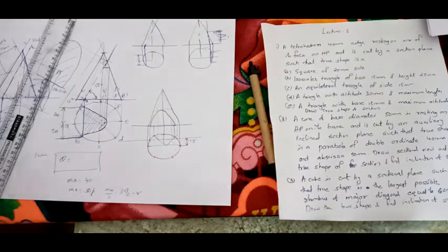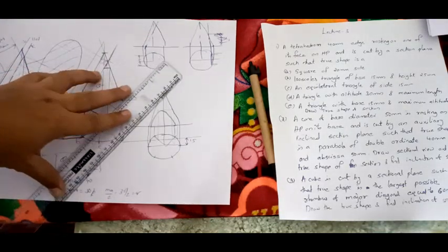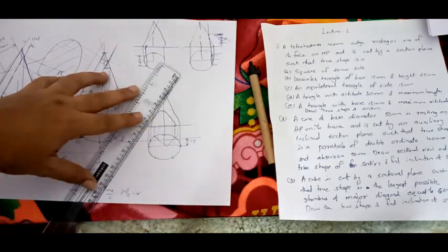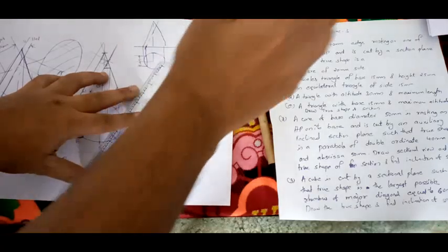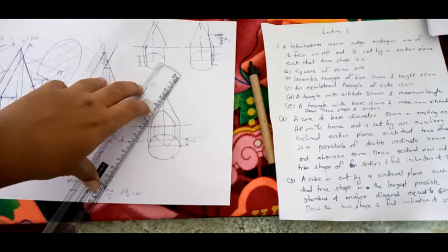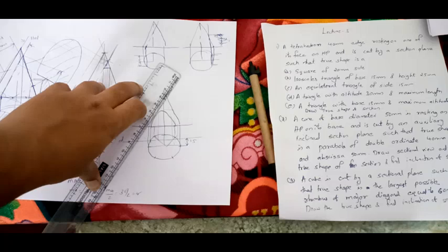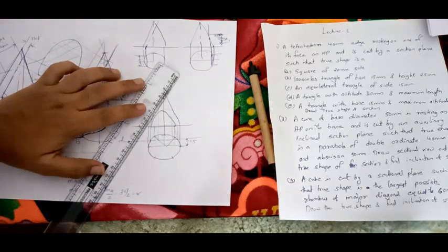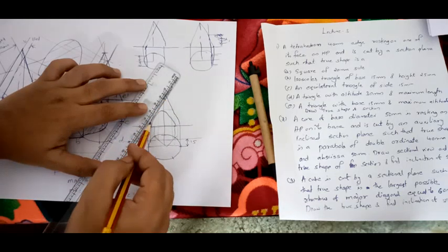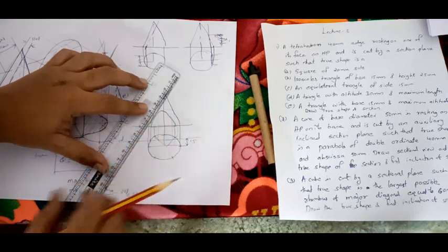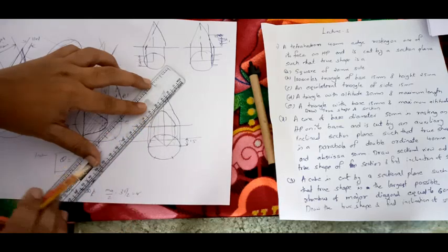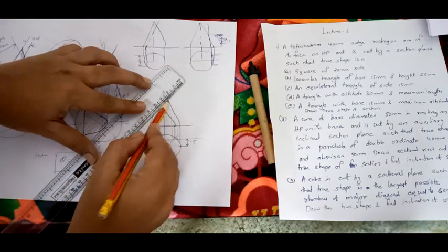Now what you have to do, listen carefully, you have to draw a line in such a way that this line should be tangential to this hyperbola and length equal to your major axis. Now see how, by trial only you will draw this. See, this is tangential, right? So this much distance is here 2.56, it's not equal to 40 mm. Now what I will do, I will rotate, I will place like this in such a way that still the scale is tangential to this, and finally this will be equal to 40 mm.